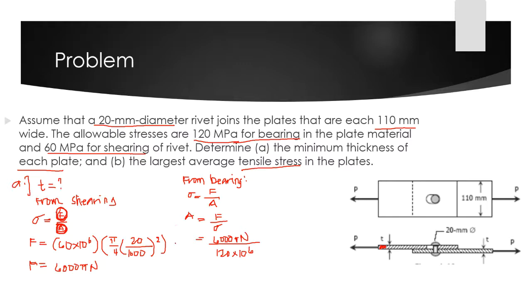And for the area, as we know, the bolt is 20 millimeter. So that's 20 times the thickness, length times width, so 20 times t.